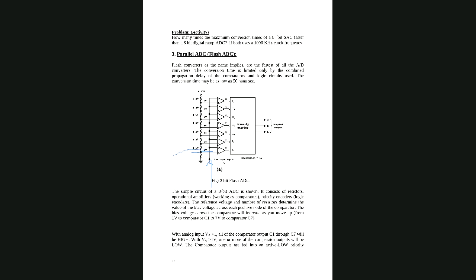I will discuss what will come here. It will compare. If the input is more and the reference is less, it will give you 0 because the input is going to the negative terminal.